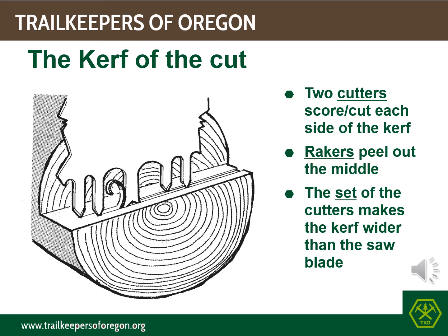A special kind of tooth, the raker, allows the cutter teeth to work more effectively with less effort. Even though the rakers don't sever fiber, they perform the other two functions of saw teeth, breaking loose the cut fiber and removing it from the log. Rakers remove material whether the saw is being pushed or pulled.